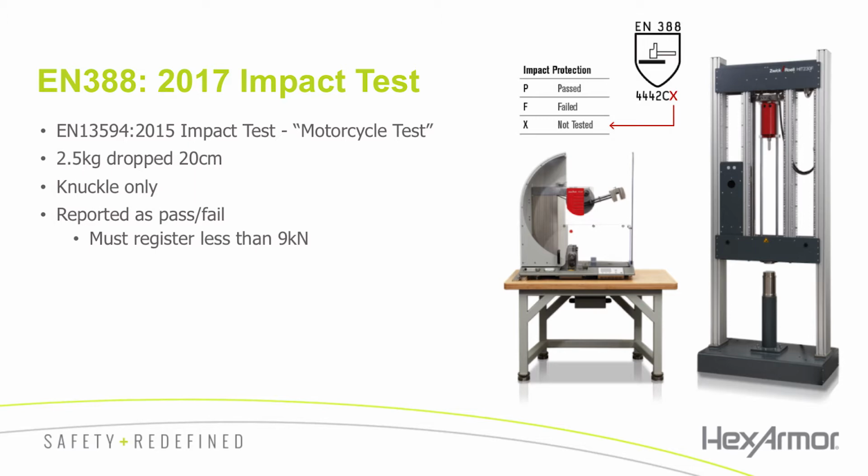The machine measures the amount of force that transfers through the glove material. So with nothing on the machine, the force measures around 20 kilonewtons. In order to pass the EN 388 standard, the glove materials must reduce the transferred force by 65%, registering less than 7 kilonewtons, or an average of 9 kilonewtons.